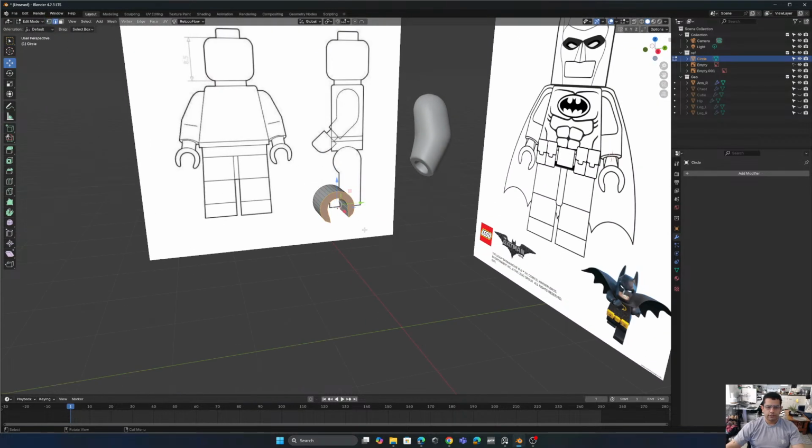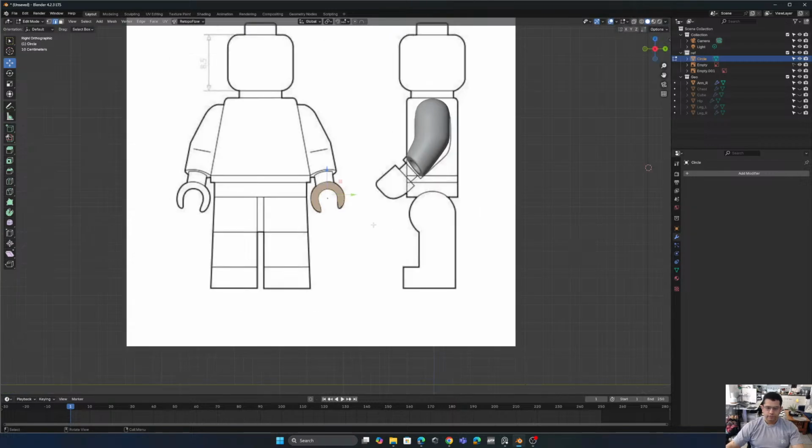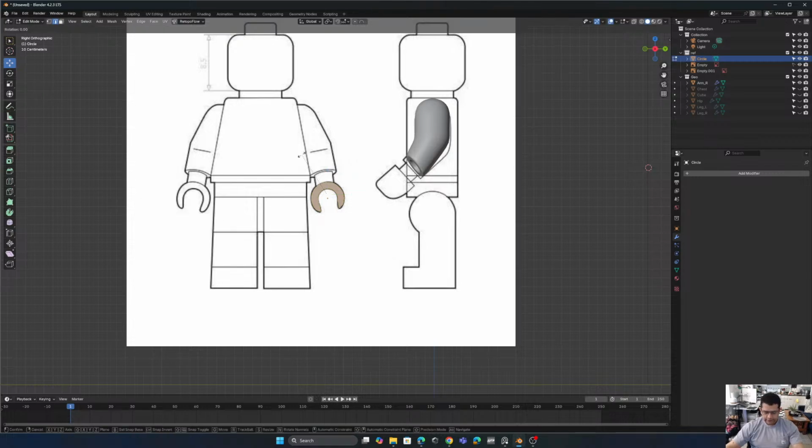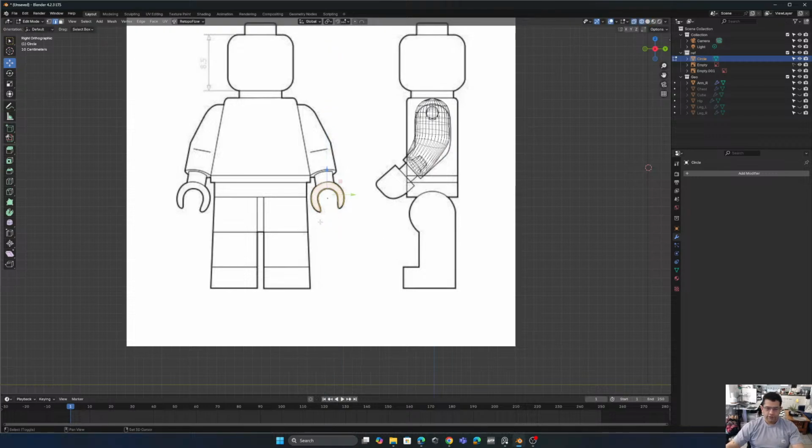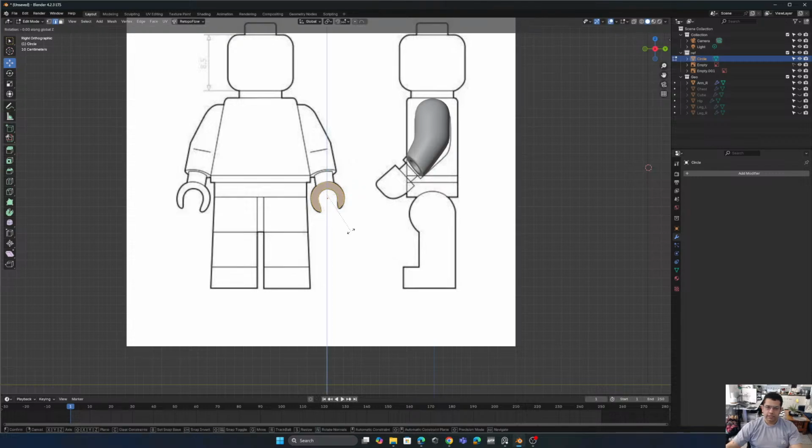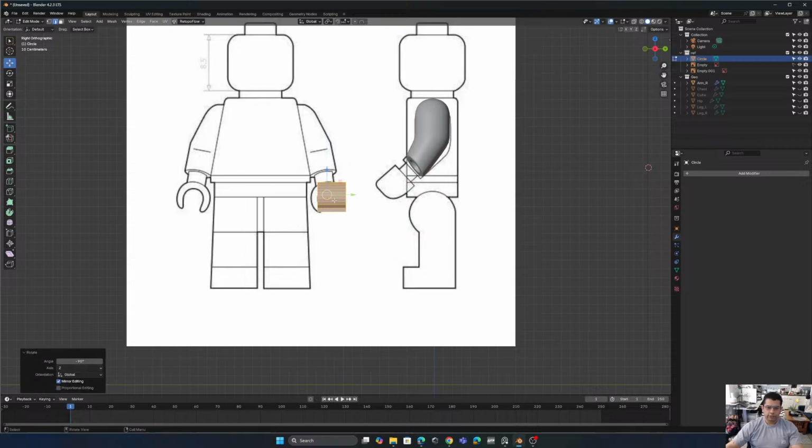We're gonna go to edge mode. We're in the side view, and we're gonna try to rotate this. So we're gonna press R to rotate and Z to rotate in the other. Oh, we're selecting just the face, sorry. Shift Z to go to wireframe, select everything. Shift Z to go to shade mode. R to rotate. Z to select the axis. Control to move in angles. And we already rotated that.